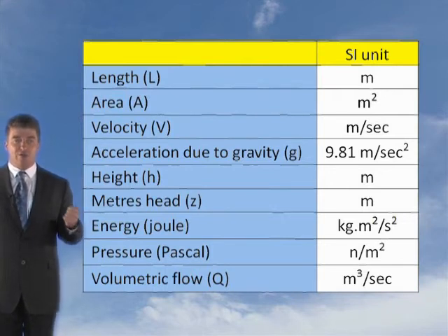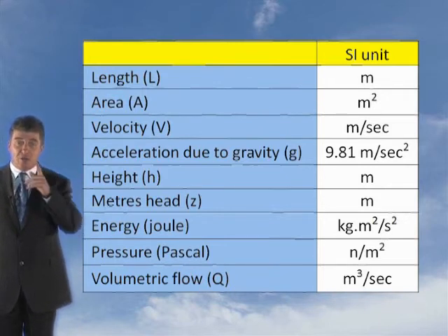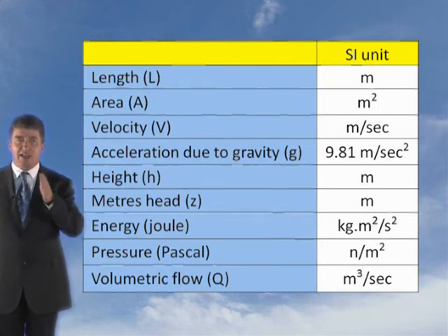And the volumetric flow, Q, is always in metres cubed per second. Again, don't forget, metres cubed per second. People get that wrong. They do it metres cubed a minute. It's metres cubed a second. They are the SI units. Convert any information given to you into those forms as soon as you can before you start applying it into Bernoulli's. That's tip 2.